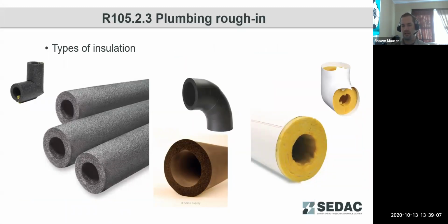One of the things we like to call out as best practice for plumbing insulation, there are different types. No matter what type you use, mitered corners or formed corners are good to use on that insulation. This provides some additional benefits in that your thickness is maintained for that insulation, so you're maintaining full R value. For any refrigeration or cold water piping, that's going to reduce your risk of condensation as well. It's going to relieve stress on that insulation so that seams can't split apart. It's going to reduce the potential for long-term damage to that insulation due to those stresses of being compressed and stretched.